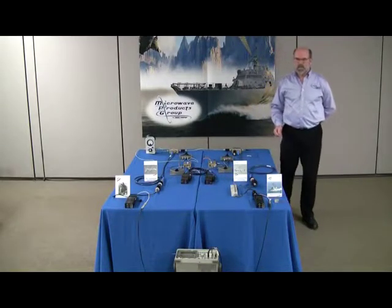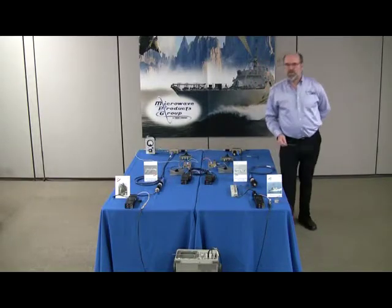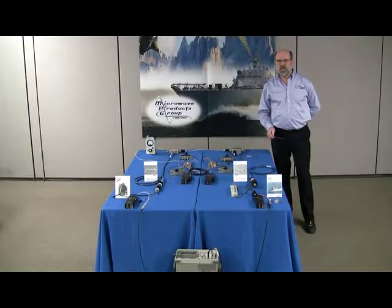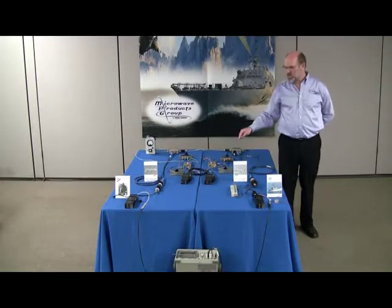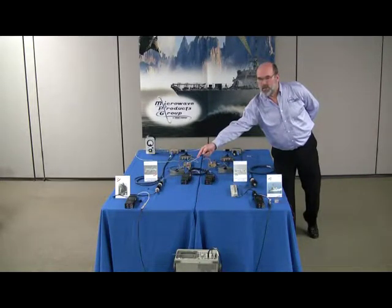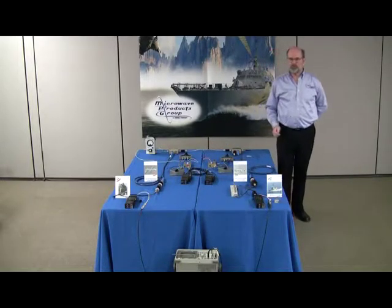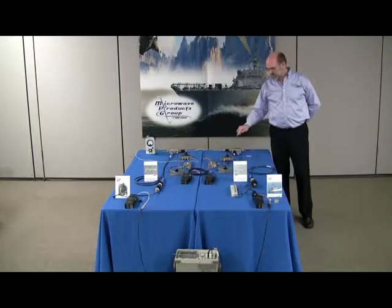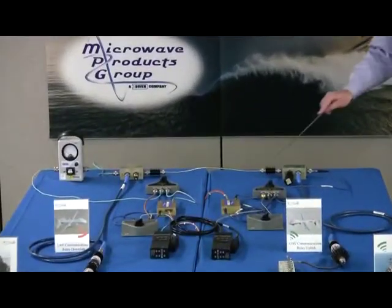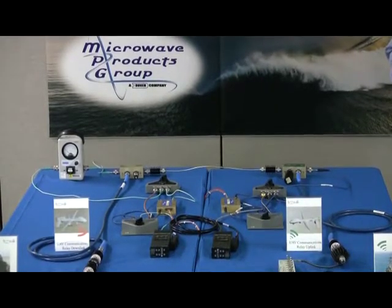Each link is composed of significant attenuation to lower the transmitter's signal to levels appropriate for reception. The demonstration will measure the attenuation between the uplink transmitter and receiver required to get a minimally acceptable audio signal quality at the downlink receiver, with or without Cosite interference mitigation. The RF switching on both links, shown here, will either apply or bypass Cosite interference mitigation hardware to these links, and we will observe these effects.